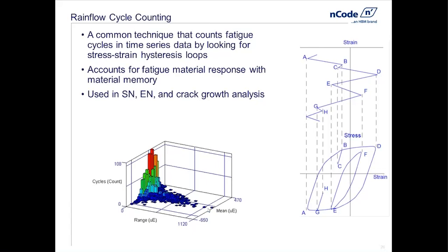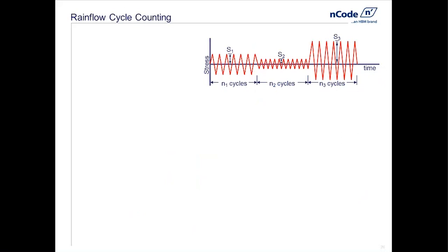So let's think again back to this cyclic stress history. The stress life curve, or the strain life curve, would allow us to say if the cycling was just like this, how long until failure occurs? Or, if stresses were just like this, how long until failure occurs? But what we've missed so far is what happens if the stresses are like this for a while, and then like that for a while, and then like that for a while. This leads to damage accumulation and Miner's rule.